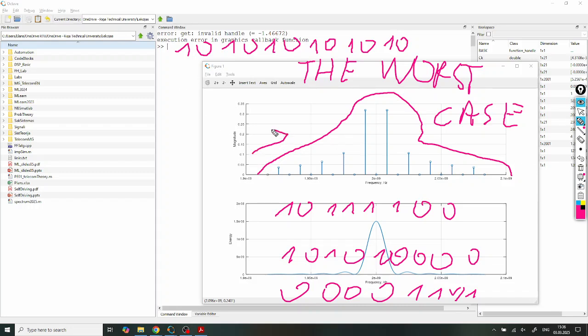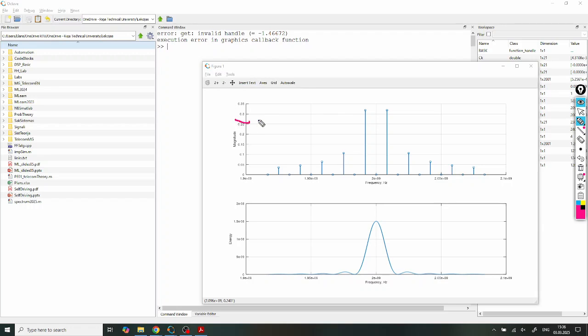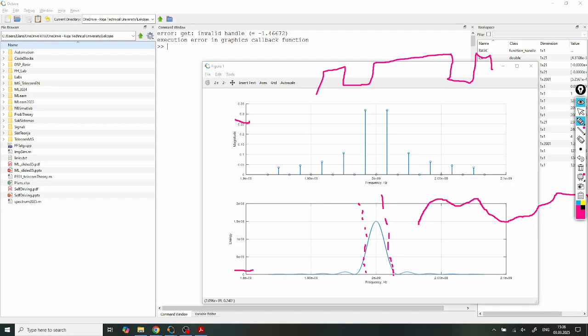Yes, that's why we need specifically this spectrum, which is for the worst case scenario in terms of amplitude, how the magnitude is distributed in the signal, and this one to get the total impression of where exactly most of the energy of your rectangular shaped signal is focused. So you see that most of the energy is in quite a narrow band, and these can be considered leftovers, insignificant leftovers, which can be filtered or even cancelled, ignored. And you still will get a decent shape of your signal, which you can then take readings from.